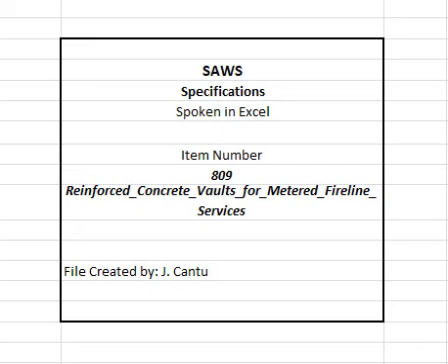1. Certifications. A. Per General Conditions Section 5.12.2, all contractor submittals for all materials furnished under this specification shall be marked as reviewed and approved by contractor for compliance with contract documents and the referenced standards. B. Submit proposed mix design and test data for each type and strength of concrete in work. C. Submit laboratory reports prepared by independent testing laboratory stating that materials used comply with requirements of this section.